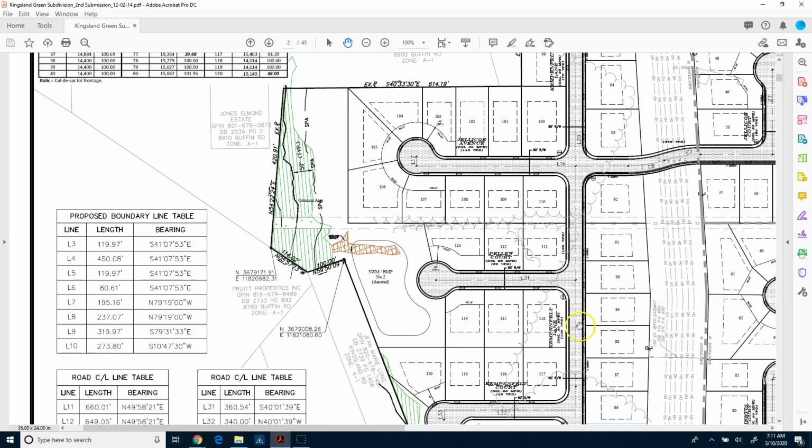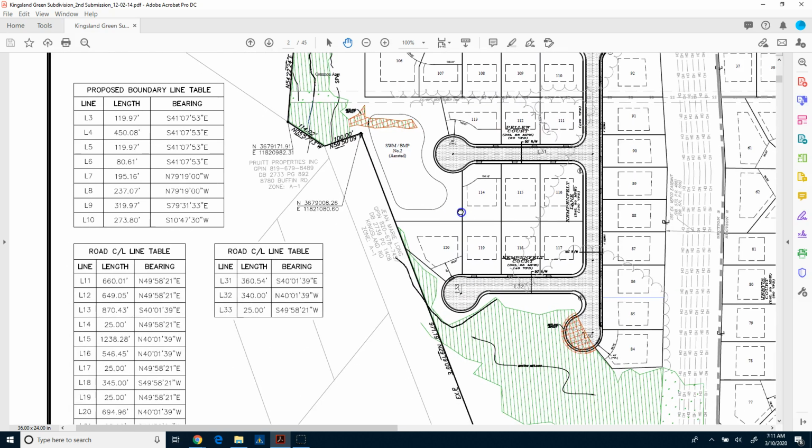Now, this is a plan set in Virginia. It's a requirement by the surveyor to put in coordinate values and even monument where the property information is. So we could use these if there happens to be monumentation out there and we got a clear area. If this was actually a concrete monument or an iron pin or a rod, we could actually maybe use that as some of our control on this project.